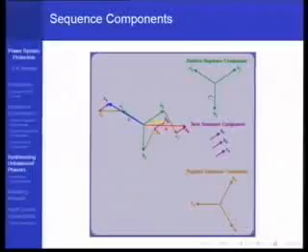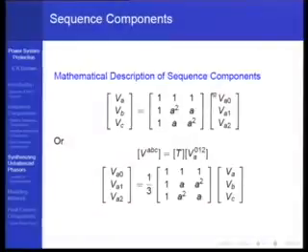So if you just give the same current excitation to the 3 windings, the net MMF created in the air gap by symmetry would be 0, because the winding is distributed and the currents are identical. In the air gap the MMF created would be 0, therefore there will not be any rotation. Okay. So these are animated pictures in the web course, you can look at it.